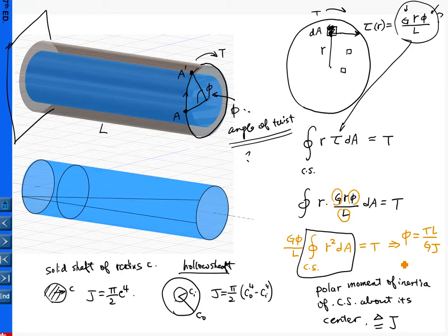So by doing this, we have solved this one. And once phi is solved, and that is the angle of the twist, whenever we are given the torsion, we know the dimension L, we know the material properties, we know the geometry. Basically, this is determined. So we're back to here. So tau, once we know this one, then we can see what is tau. So basically, tau equals G times r over L, and then we introduce phi here.